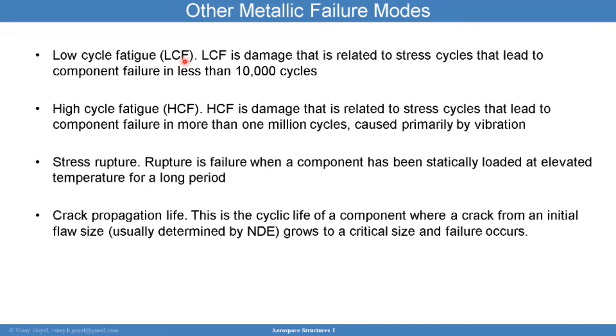really accelerates that failure. Just take as an example a little aluminum wire, and you bend it back and forth quite dramatically to cause plastic deformation. Well, in those scenarios, you're going to have some amount of damage getting accumulated, and failure will occur fairly imminently below 10,000 cycles.